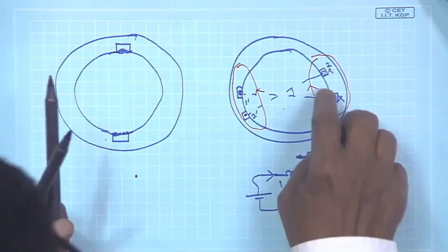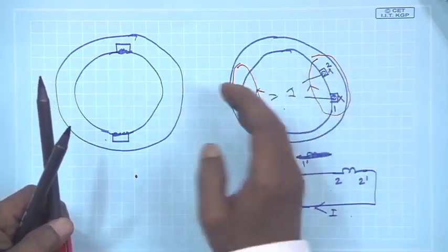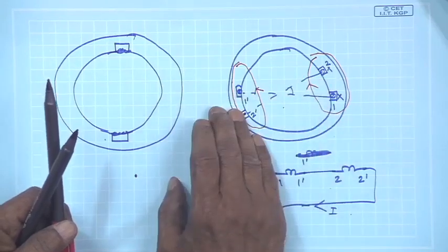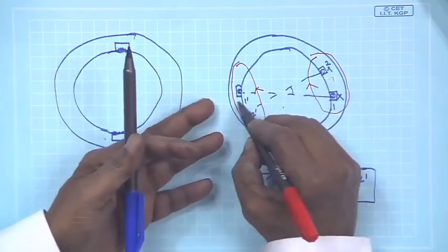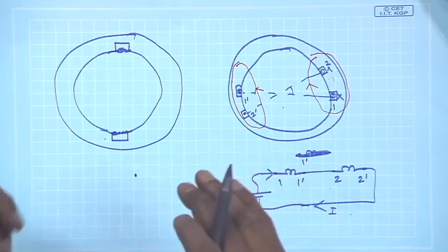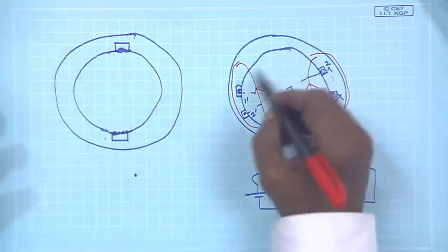Therefore, any band of cross current distributed over space and opposite side dot currents which are also equally distributed, in effect it is as if a single coil in the middle is producing a field. So, each one produces two poles, and the resultant will be like this.